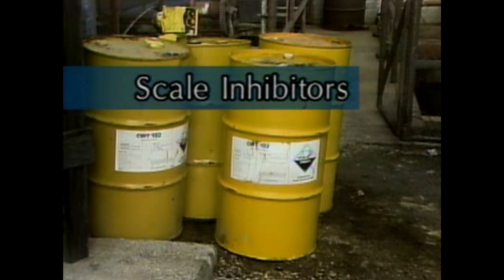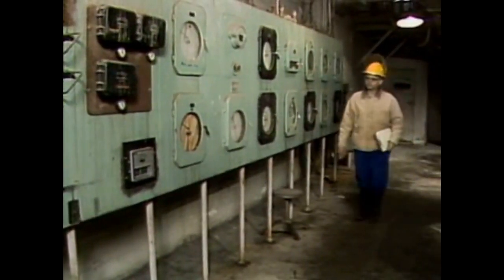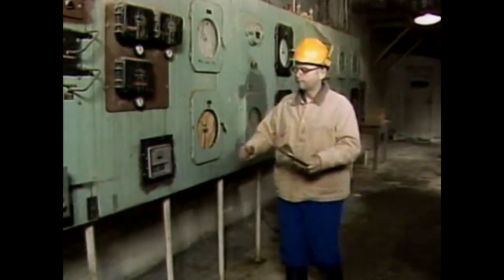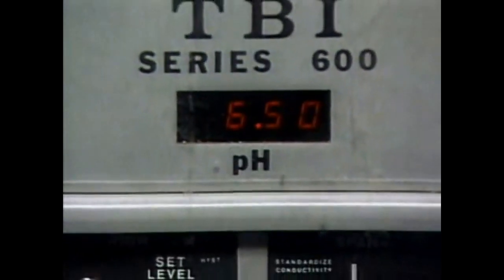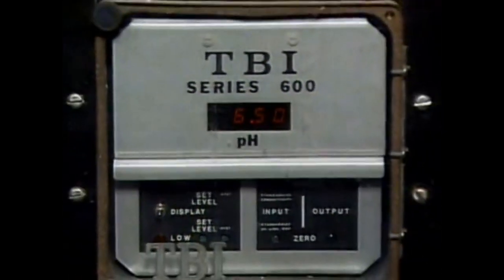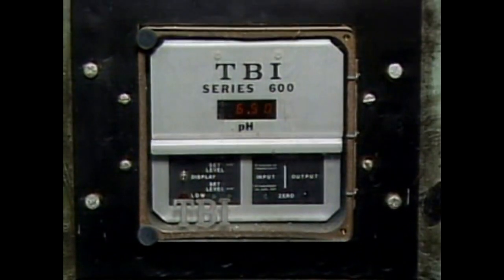Other chemicals may be added to control the water's pH. The water's pH is an indication of its acidity or alkalinity. A low pH means the water is acidic. A high pH means the water is alkaline. A relatively low pH tends to increase the likelihood of corrosion, while a relatively high pH tends to increase the